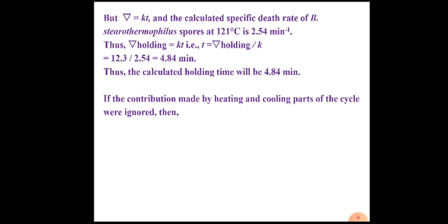That means here we are not considering del heating, del cooling. We are not considering the contribution made by heating and cooling in relation to the destruction of microorganisms. We are only considering that the destruction happens only during holding period. Let us see what happens.